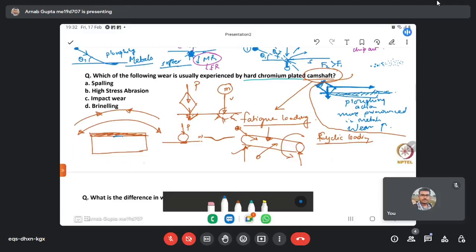and there will be cracks on the, like if you see from here, there will be failure between these two, coating and the substrate, and also in the coating due to this particular action. Like first it will initiate at this surface, because it will try to slide onto each other, because the properties of the coating, the interface and the substrate are different, right? They are having different strengths.